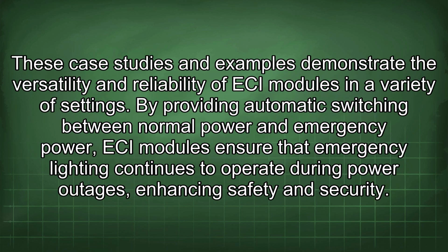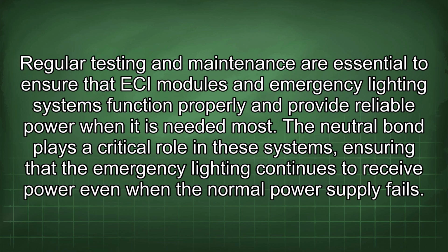These case studies and examples demonstrate the versatility and reliability of ECI modules in a variety of settings. By providing automatic switching between normal power and emergency power, ECI modules ensure that emergency lighting continues to operate during power outages, enhancing safety and security. Regular testing and maintenance are essential to ensure that ECI modules and emergency lighting systems function properly and provide reliable power when it is needed most.